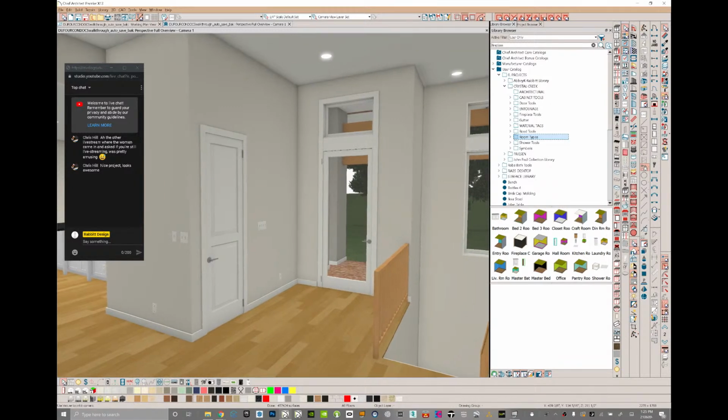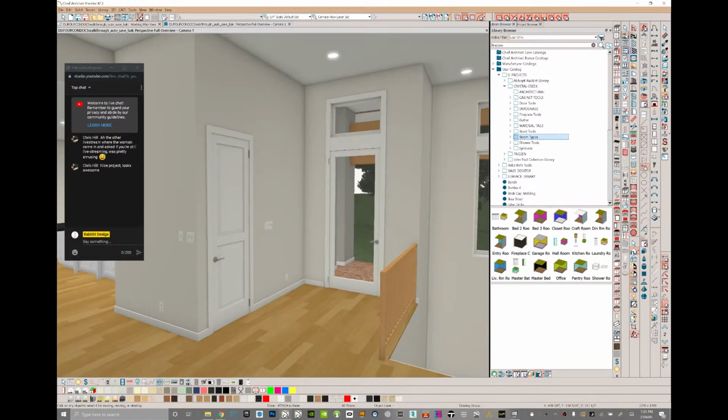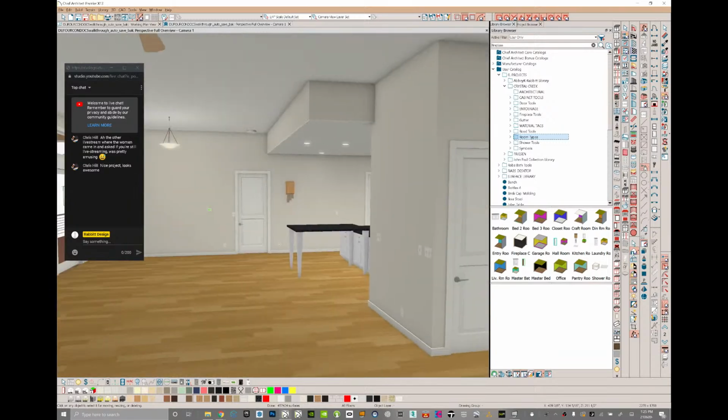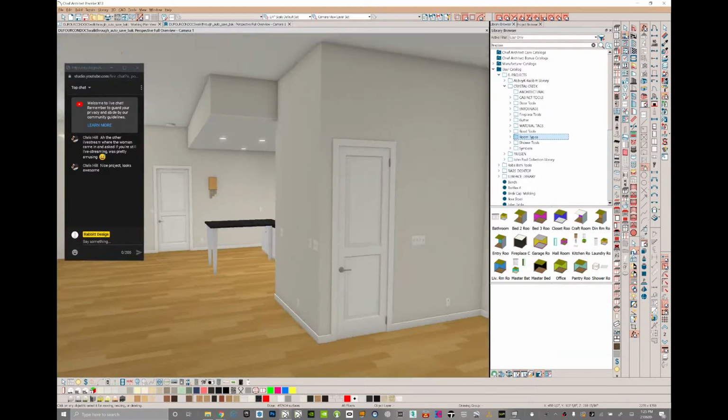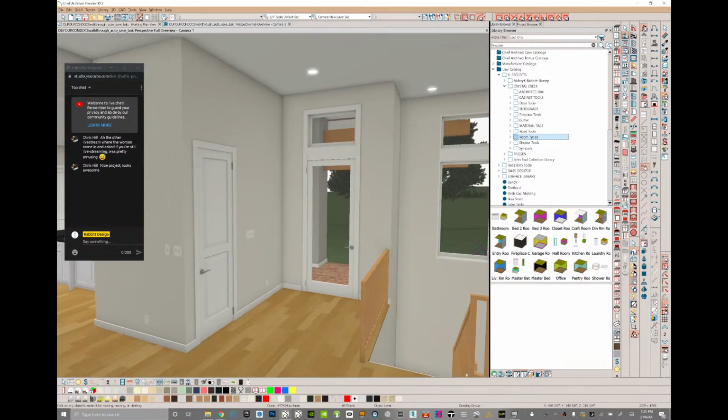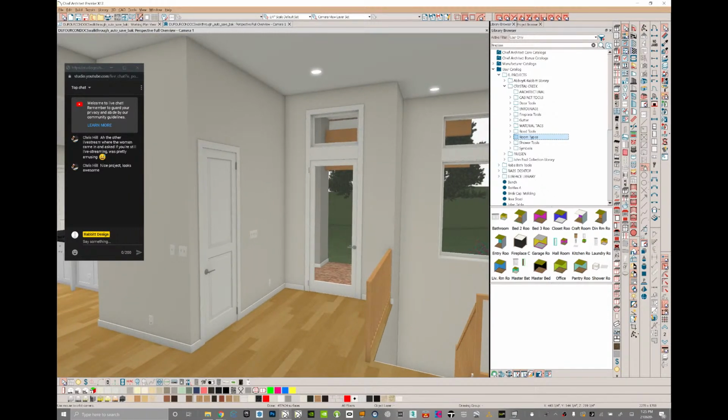But when you export this to Twinmotion, that material ID will be shared with anything else that is painted with the same material, which means I can't change one wall from the next in Twinmotion without some workarounds. So if a wall carries through, even though it's interceded by an adjacent wall, that material will still carry through the wall in Twinmotion.